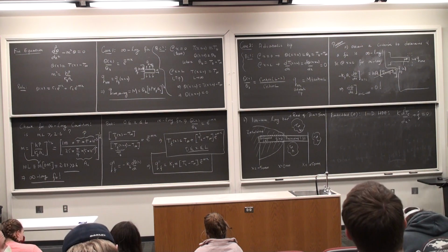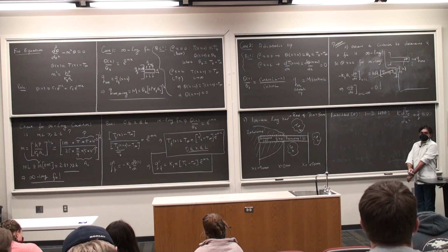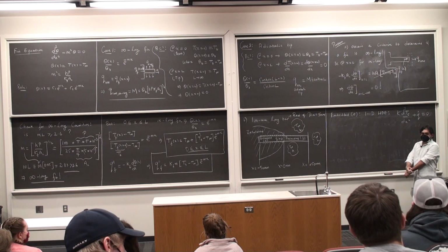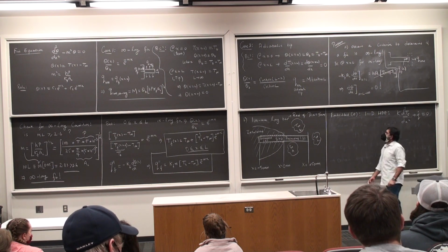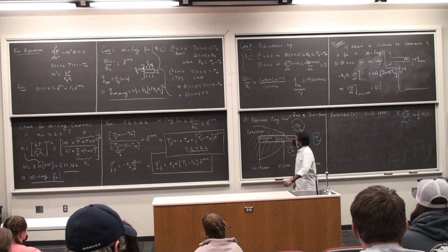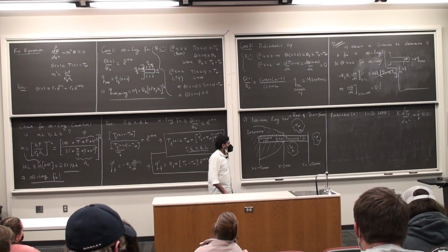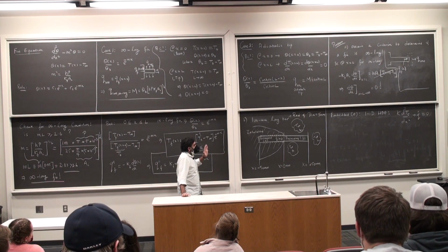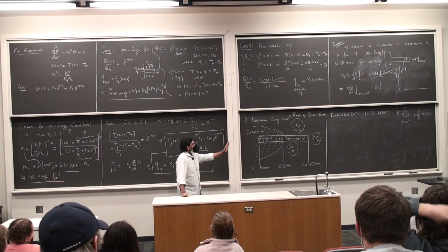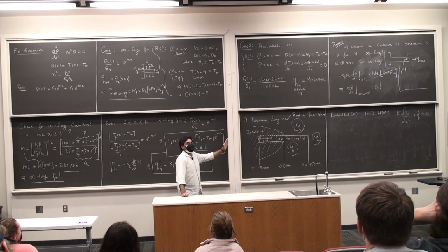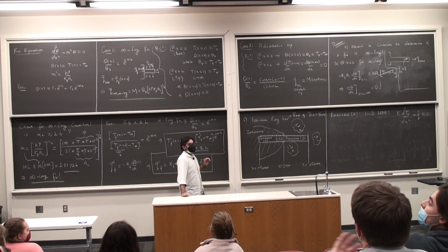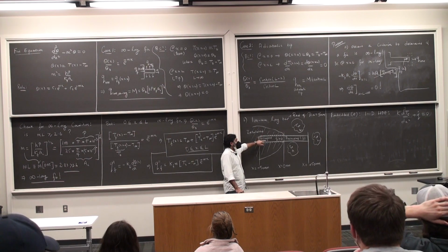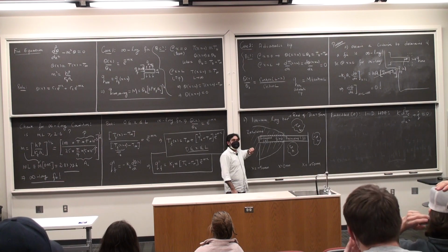Yes sir, question. Why don't we use the HDE for a cylindrical body? Because isn't it a rod? Right, but then you can think of it that way. We could do it that way, but let's see. Your direction of heat transfer is along the length here. So we don't care about the radial direction. If we care about radial, we use that one. Because of the fact, you see, cleverly they said that the top and the bottom are also insulated, besides the side.